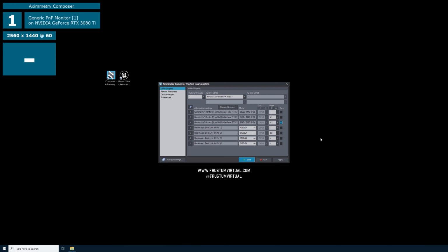If you are sending multiple video signals through HDMI or DisplayPort cables, you can index these outputs to 3, 4, 5, and above. Just make sure that you're setting sync on the first HDMI or DisplayPort output.